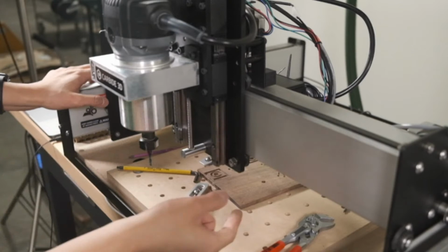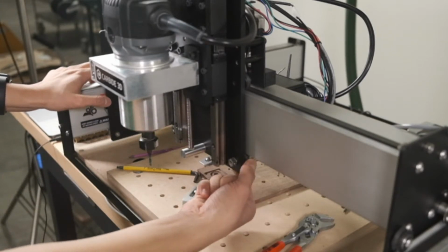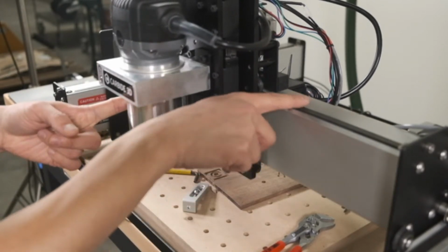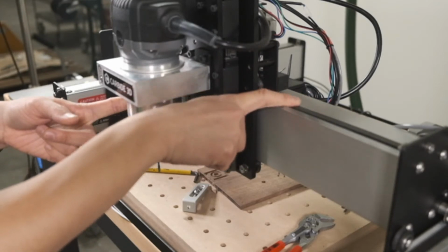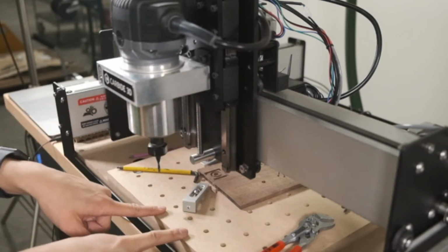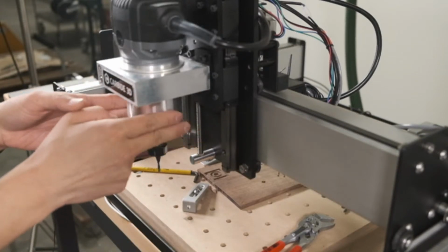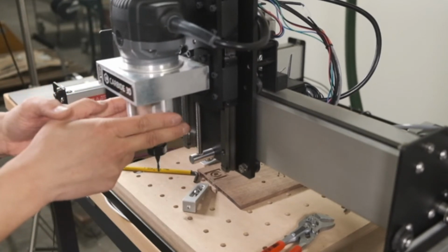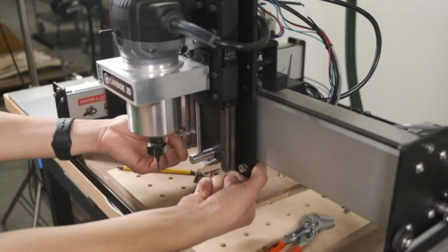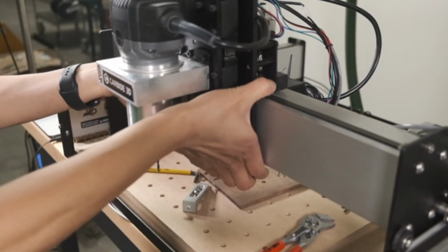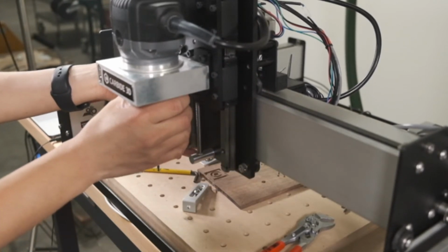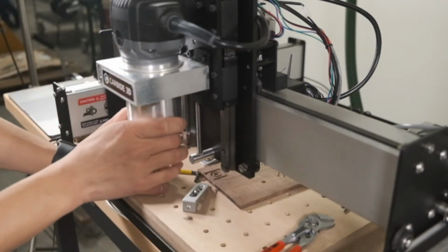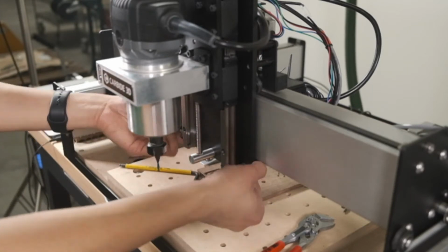At my machine at home, I have accidentally tightened these down way too much. And what happens is there's a lot of resistance when you push. And because of that, you can actually develop backlash from the belt even if this is properly tensioned. So I was trying to engrave some really tiny features, and so the machine needs to be able to move back and forth in really small increments really well. And if you have any backlash at all, that's going to ruin your engraving. So if your wheels are too tight, they sort of just lock down your spindle, your gantry, your carriage, and that can cause your features to come out just a little undersized or oval or just a little sloppy. So do not over tighten your V-wheels.